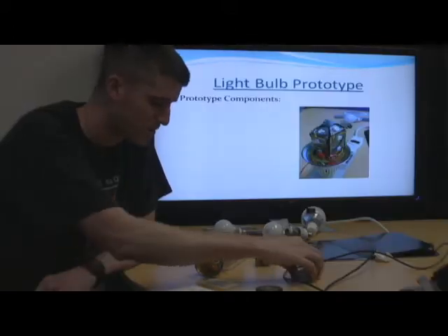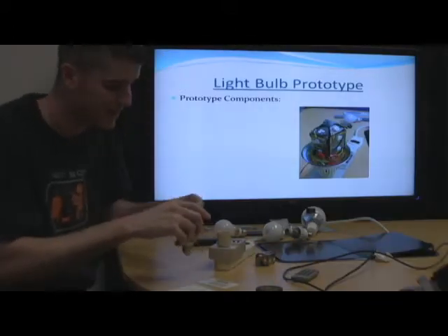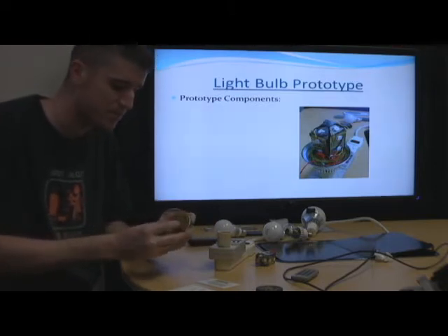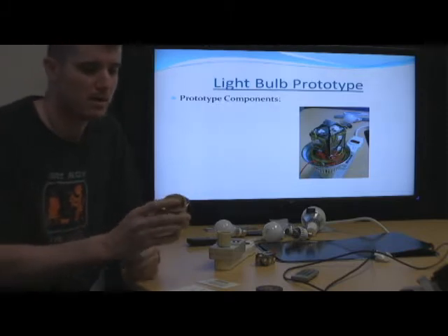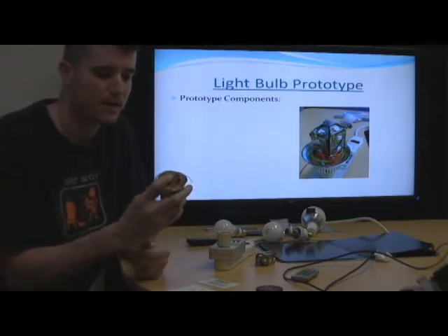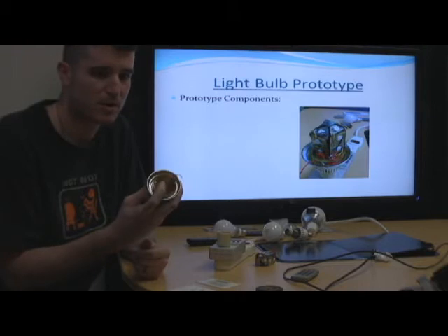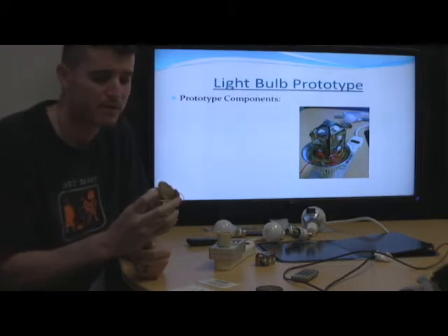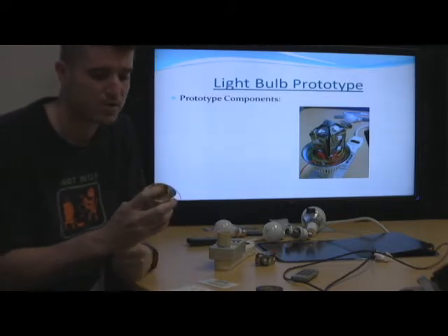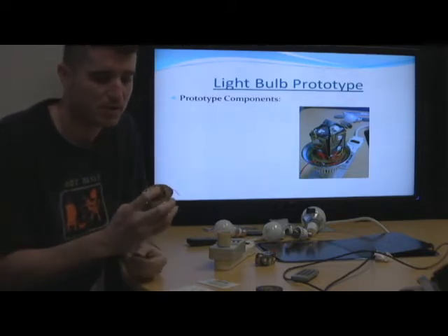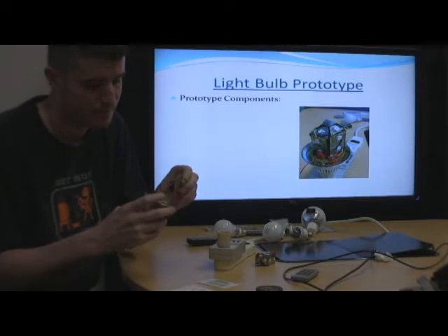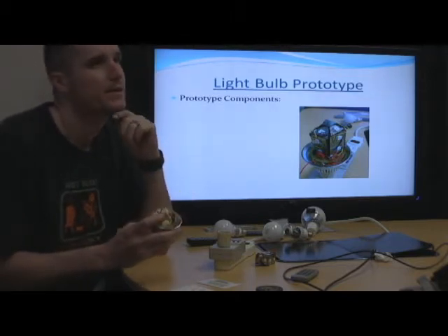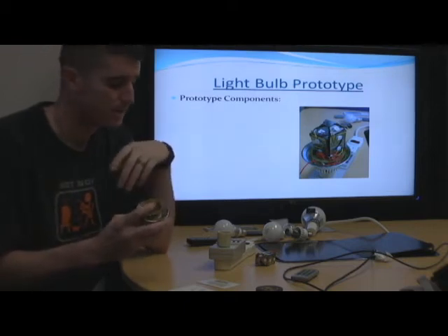Let's go over our preliminary prototype. So this is our first prototype that we did. The power supply pretty much didn't change through to our second prototype, except we cleaned it up and put in some smaller components, surface mount components instead of these through-hole components, which shrunk the power supply pretty well. And we went to a solder mask as well, so it looks a lot cleaner.